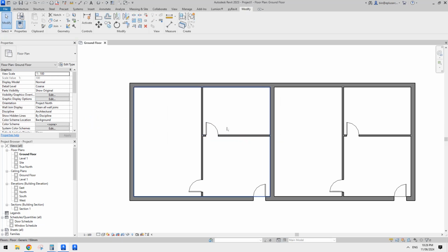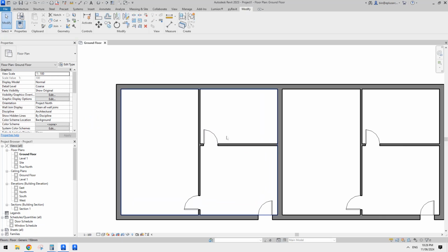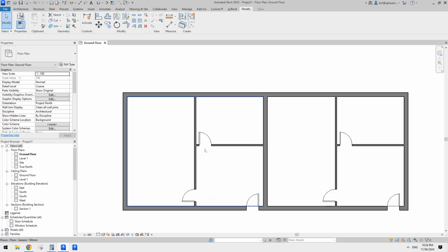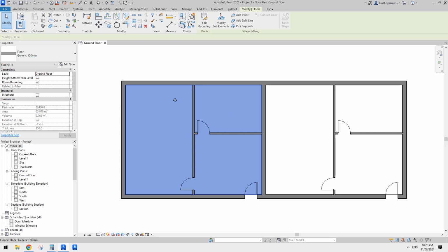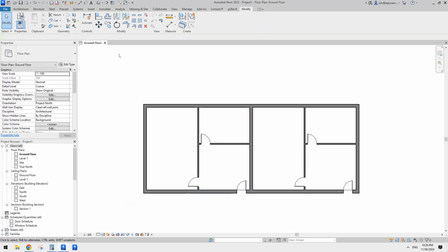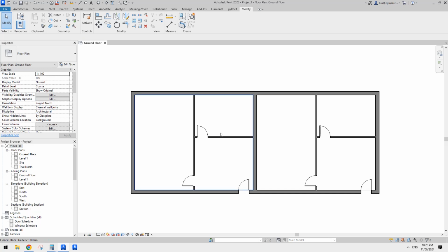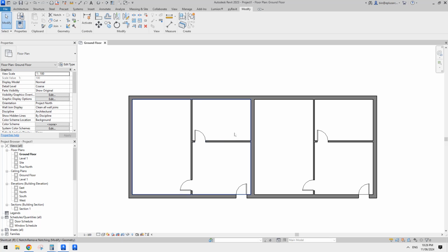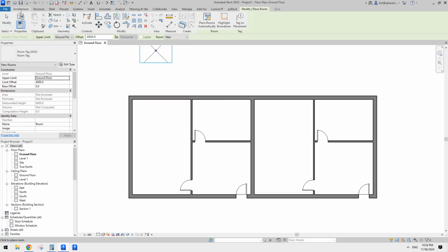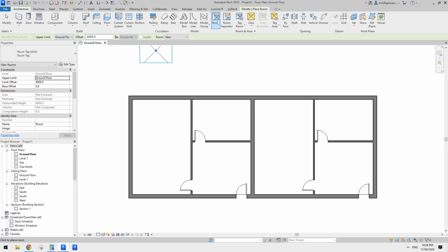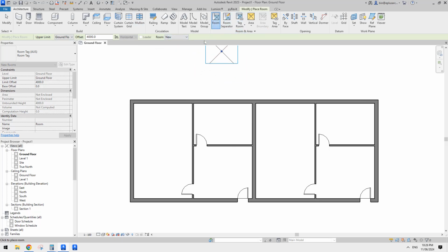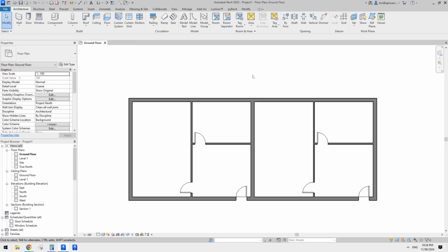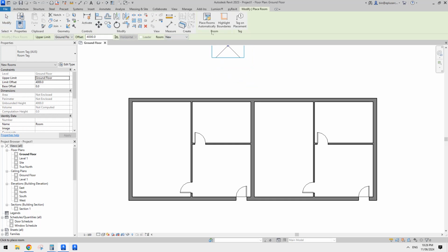Usually at early stage, we don't apply materials to the floors, or we just use generic floor. We can use room to apply floor finish patterns or color. So you can do this. Usually type room, RM. So if you go to architecture, room. And then once you type this one, you can, actually hang on, RM. So this is quite useful.